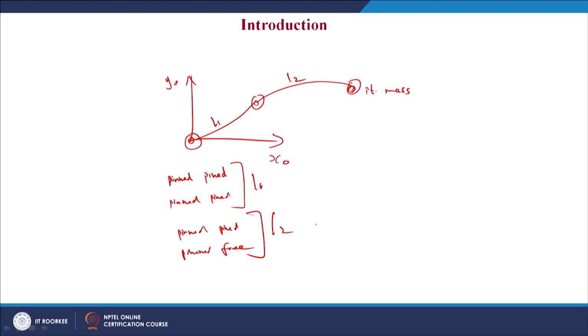This is how it becomes, and there are variables: the joint angle, in the case of rigid links, and another thing called deflection. We can say delta i, precisely Wi, which is a function of xi, where xi is a point along the flexible link. This is the deflection of the flexible link, and we know the rigid case is based on joint angle theta.